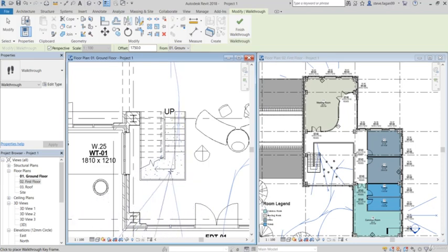So the ground to first floor level is 3 meters, so half that is 1500. Add that to the 1750 gives us the 3250. So now when I place my camera at the half landing, I know that I'm level. And now before I click again to be at the top of the stairs, I must change back to the 1750. And as well, I must change the offset.